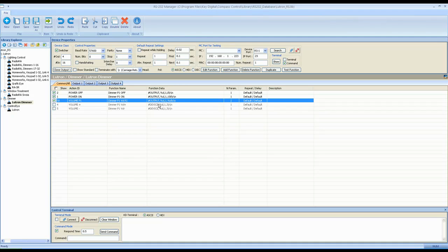And you see, actually, this is a command with 2 parameters. It is set here, number of parameters is 2. And the second command, where you see the second %d, is going to be the current level set of that dimmer, just as we had shown a minute ago. So this command features two local variables. Local variables meaning there are 2 parameters, and they are determined locally within the control interface by the user.